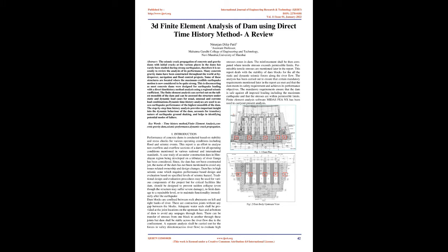a regional seismic coefficient. The finite element analysis can be carried out on the tallest monolith of the dam and can be used to assess the structure under static and dynamic load cases for usual, unusual, and extreme load combinations. Dynamic time history analyses are used to assess earthquake performance of the highest monolith of the dam.